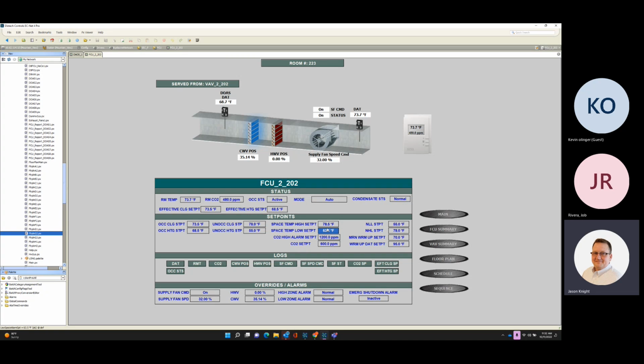You've got your alarm set points that you guys can adjust. Well, you can override or put them back to auto. The spec said 5 degrees above and 5 degrees below, so that's what we did. And then we made it so, let's say you wanted to do something in a room and instead of 78, you want it at 77, just do your override or your timed override for however long you want to test it.